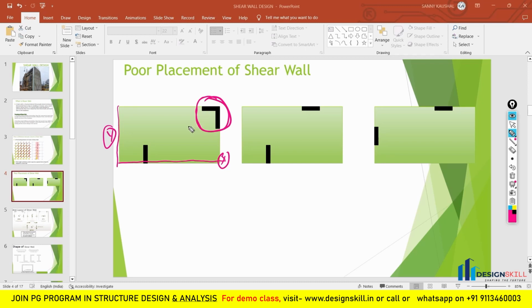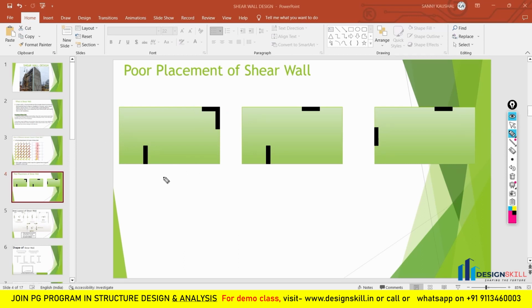Now, what we have studied is that the lateral stiffness should be distributed uniformly in your structural configuration. You can find here that at the corner positions the stiffness of the building has been increased much more compared to other positions. So there is no uniform distribution of the lateral stiffness in our building. Now I am going to model the same case in our ETABS model.